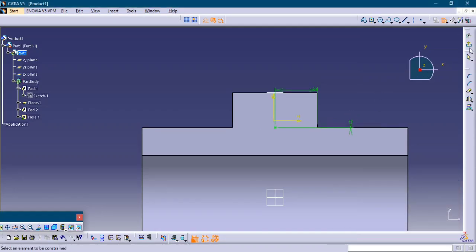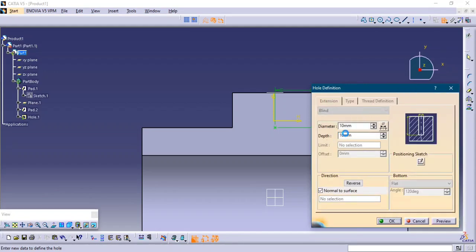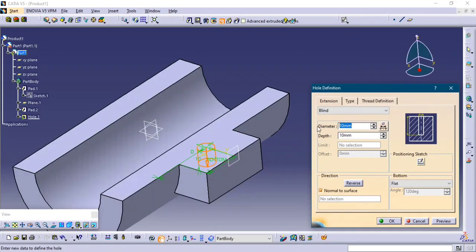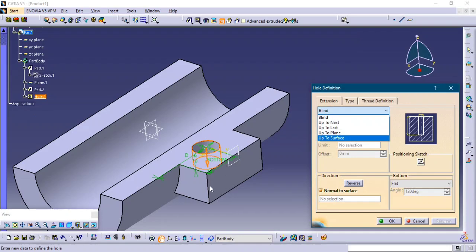right click. So or else you can give 0, or else you can give coincide relation. Click on exit, update the hole diameter. So it is not given in the drawing, so take whatever it is, you can take.